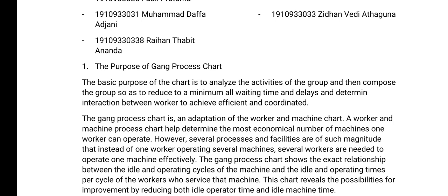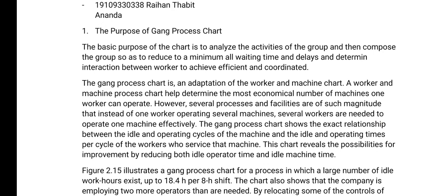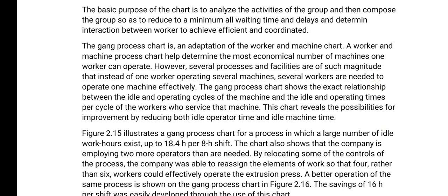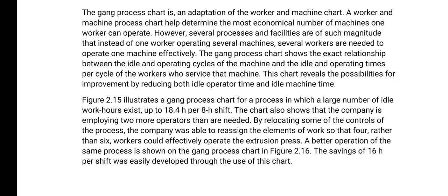This chart reveals the possibility for improvement by reducing both operator time and idle machine time. And we will see the illustration of the gang process chart for a process in which a large number of idle work hours exists, up to 18.4 hours per 8 hour shift.